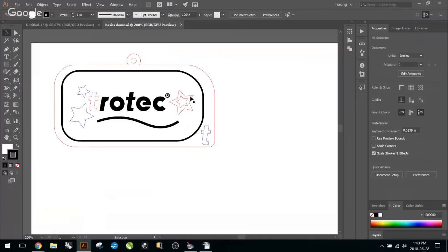We'll show you how to do that when printing, but before doing that, we'll show you with your colors. You're going to want to engrave your blue lines first, for that exact reason that we just mentioned. Sorry, you mean the kiss cut, the blue lines first? So we're going to be kiss cutting these lines first, and then cutting our base out afterwards, so our base doesn't fall and our kiss cuts fall onto a place that they're not supposed to.